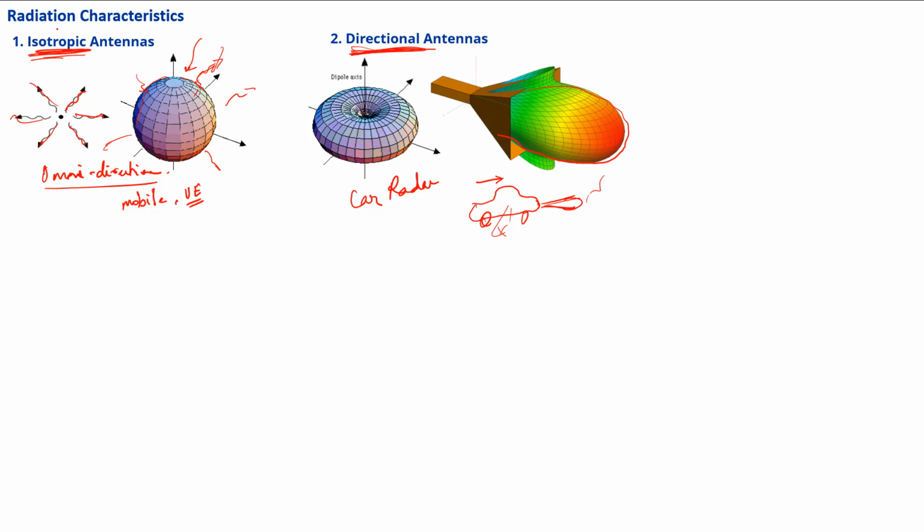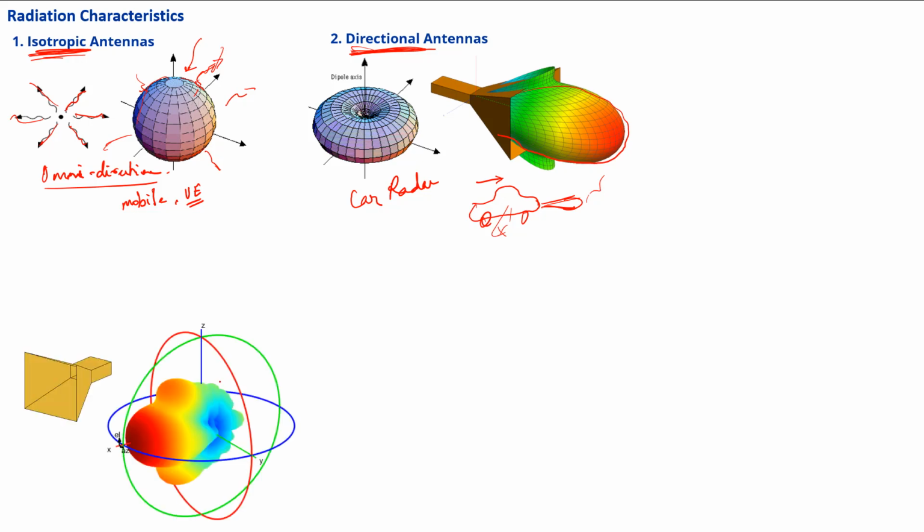So the radiation pattern needs to be understood, along with how the radiation mechanism works. In general it is a three-dimensional pattern with X, Y and Z in spherical coordinate systems. It is theta, phi, or elevation and azimuth. Elevation and azimuth are two different ways of specifying the angular quantities, at which angles we are looking in a particular direction, and what power is received there.